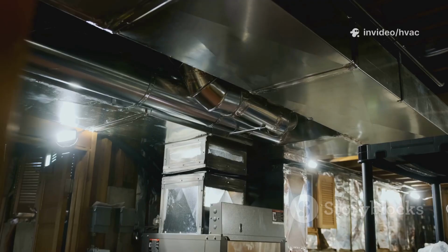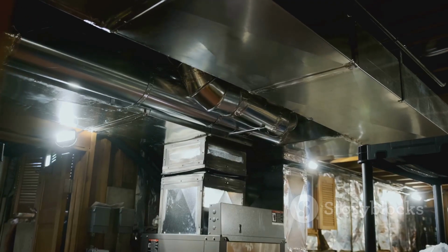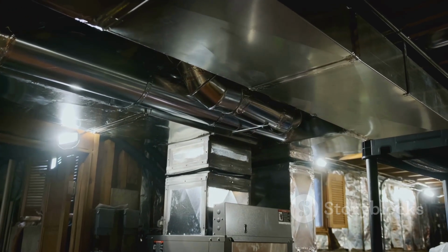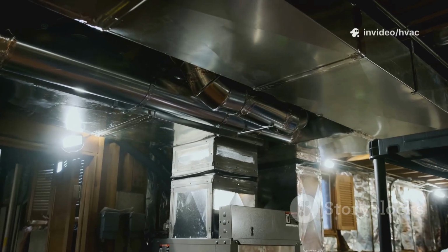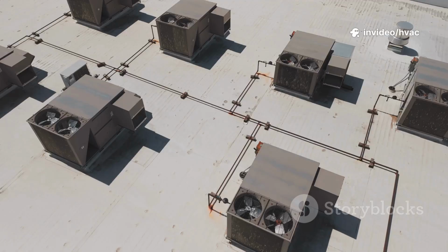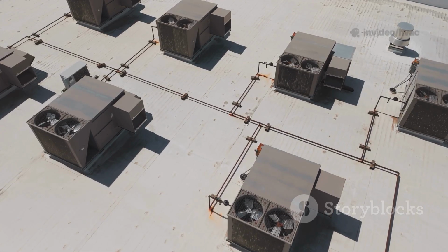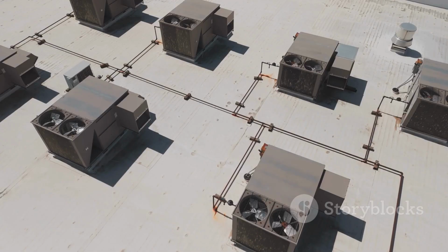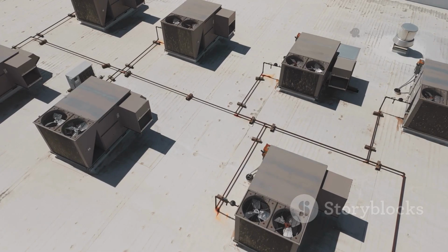Step 4. Now let's get into the installation details. First, make sure the duct is clean and accessible. Plan your sensor path so it covers as much of the duct cross-section as possible. The best method is to stretch the sensor in a zigzag pattern from one side of the duct to the other, moving back and forth across the airflow. This layout helps the sensor sample air from all parts of the duct, giving you a true average reading.